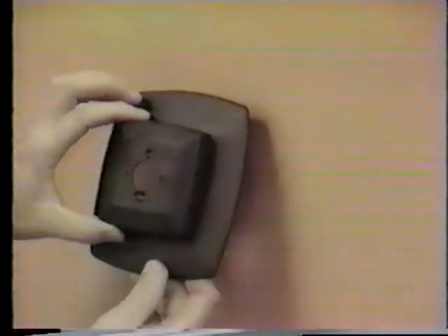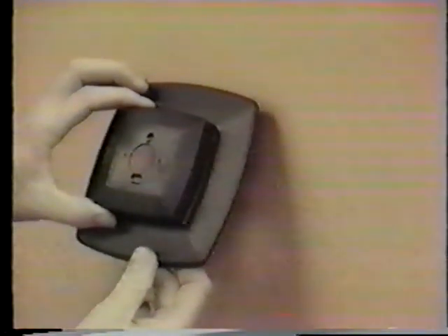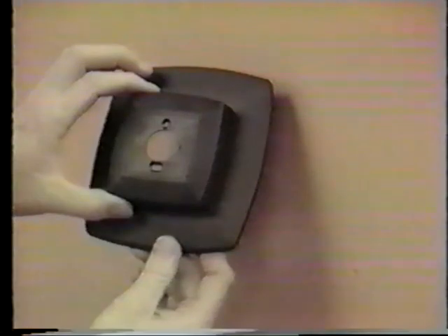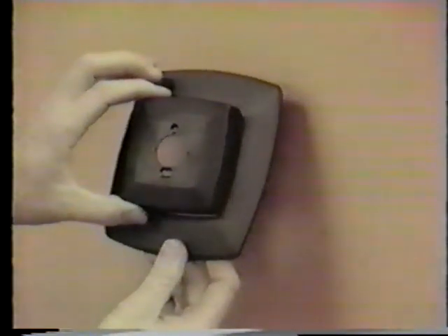Check to see if the wall plate will cover any marks on the wall. If not, plan on using the wall plate skirt. Now, check to see how much clearance is needed to clear the pipe head. It may be necessary to use the wall plate skirt to get an extra 3/16" clearance. If the skirt isn't needed for added coverage or extra depth and is not required for appearance, then break off the outer tabs on the bracket as shown here.